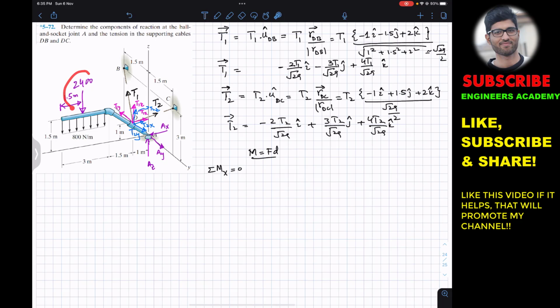So this 2400 Newton resultant is passing through the x-axis, so it's not going to produce a moment about the x-axis. Similarly, T1z and T2z, both components, pass through the z-axis, so they are not going to produce a moment about the z-axis. And these x components, T2x and T1x, are parallel to the x-axis, so they are not going to produce a moment about the x-axis. And Ax, Ay and Az are also passing through the x-axis, so they are not going to produce a moment about the x-axis. So only the y components, T1y and T2y, are going to produce a moment about the x-axis.